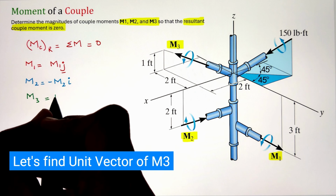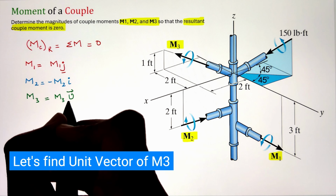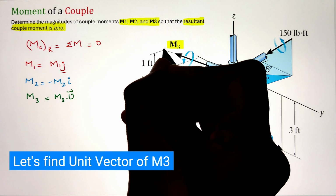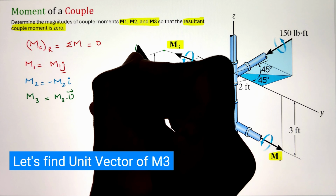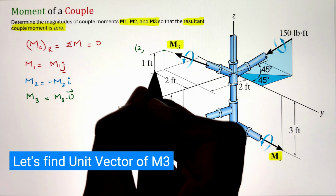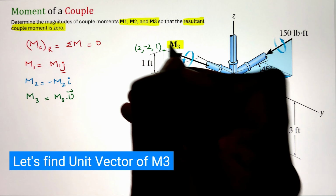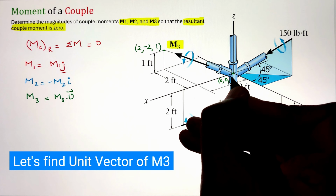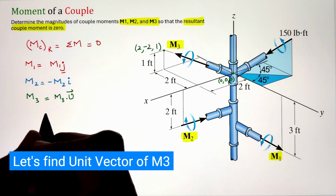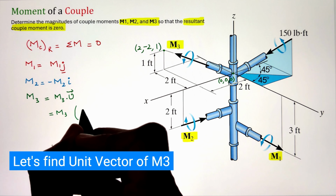Now for M3, it is acting in 3D space, so we have to identify the unit vector along which this moment is acting. To do that, we can calculate the position vector where M3 lies by calculating the point coordinates of head and tail. In this case, the head is at 2, negative 2, 1, whereas the tail lies at the origin, 0, 0, 0.